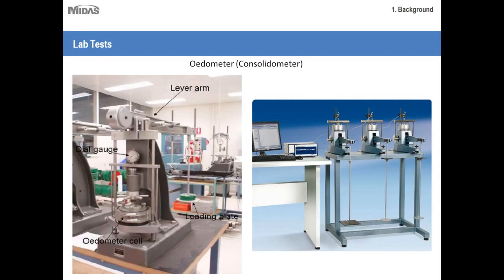Okay, so this is just a picture of the oedometer. Oedometer tests are designed to simulate the one-dimensional deformation and drainage conditions that soils experience in the field. To simulate these conditions, rigid confining rings are used to prevent lateral displacement. That's what these rings are over here. When you put your soil sample in, it'll be surrounded by this metal ring that'll support it laterally. That way, the test is a pure 1D test, so change can only occur in the vertical direction.